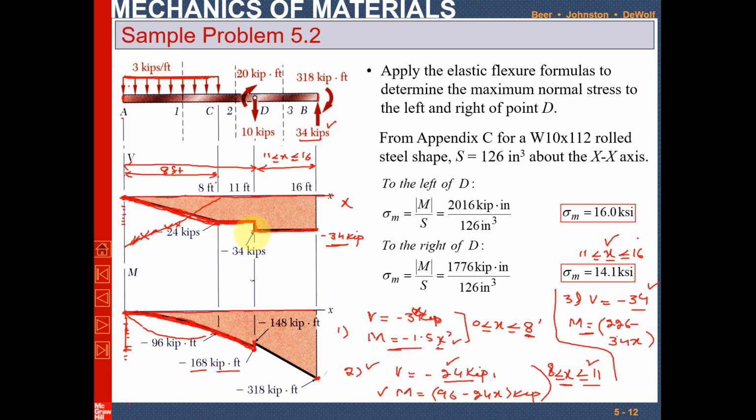Again, this is a 0 degree line or a constant number, so the bending moment will be a first degree line, or a linear equation, so you can easily join them. So this is the bending moment curve or bending moment diagram.